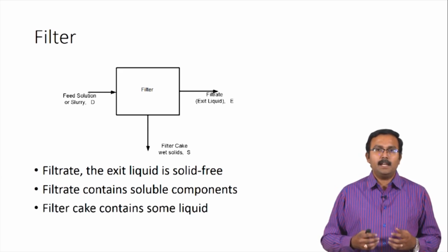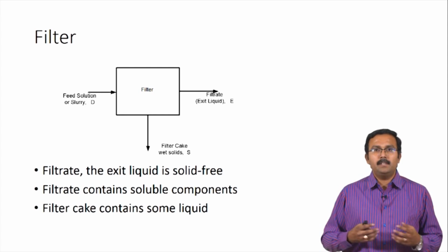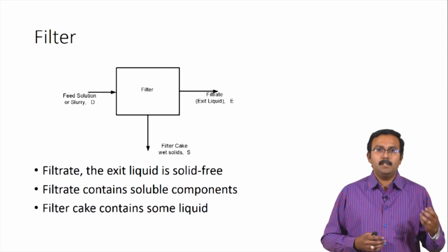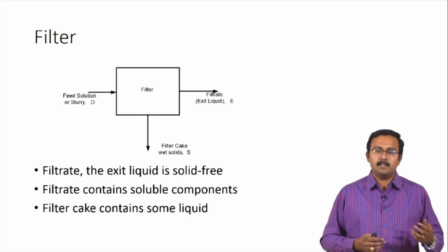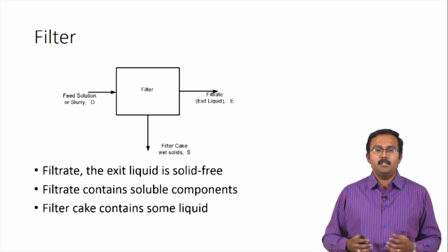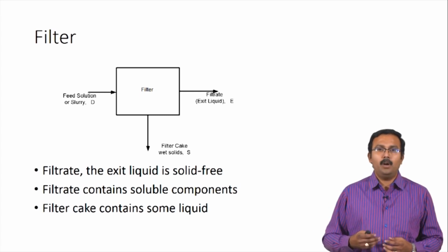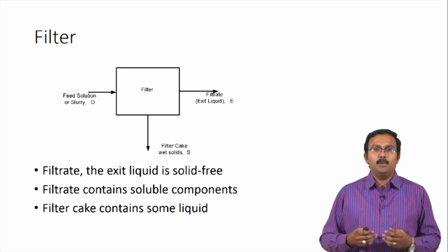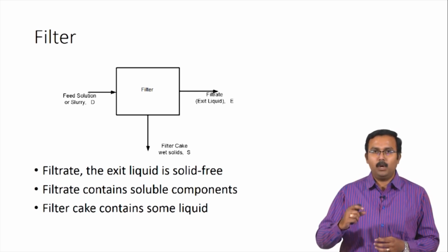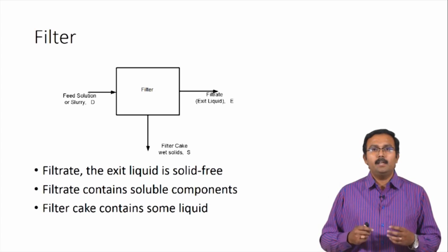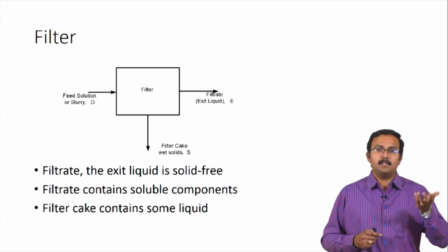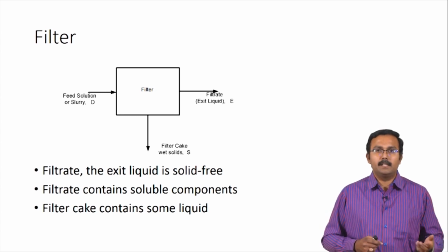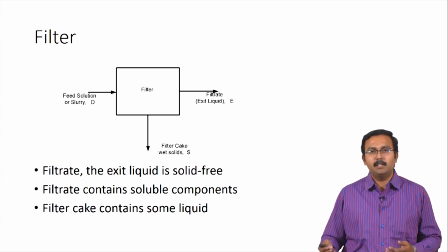Filter cake can actually contain some of the liquids. The filter cake is not always dry. It will always contain some of the liquids which are coming along with the slurry entering into the filter. Imagine this process where you have a water and sand mixture. So, this slurry, when it is filtered, you will have the liquid, which is water, collected as the filtrate, and you would have the sand collected on top of the filter paper. So, this sand will not be dry. It will have the accompanying water along with it.